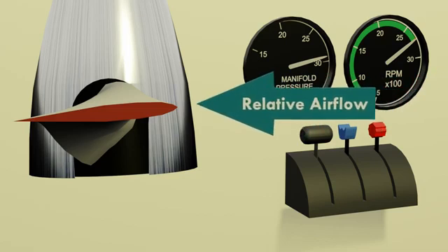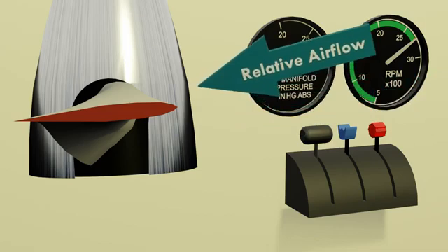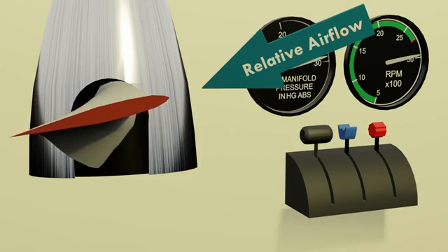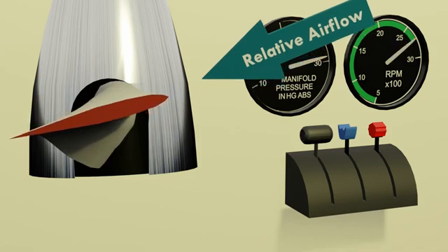As we gain speed, the propeller blade's relative wind changes, so drag will decrease. The balance between the torques has now been upset. The engine will have the advantage and push the blades to turn faster. What should the governor do? It will automatically turn the blades coarser, preventing an overspeed.